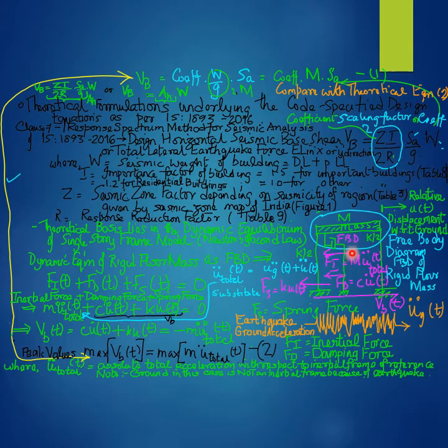Now, substituting the individual magnitudes of the three different dynamic forces under which the floor mass M is in dynamic equilibrium, the inertial force F subscript I can be written as the mass times the total acceleration in the horizontal direction of the floor mass that is considered as the free body, circumscribed by this green ellipse.